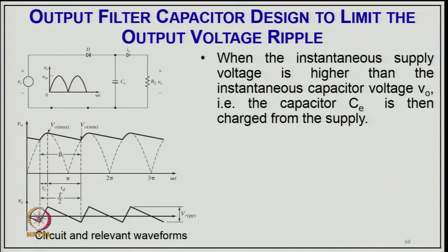And you will see this kind of waveform. As you can see here with the dotted line, this is the kind of output voltage we are getting across the load. Typically, in this duration, when your supply voltage becomes more than the capacitor voltage, the capacitor gets charged, and after that it gets discharged for a reasonably long time, depending on the capacitor value and the resistance. So, this kind of voltage waveform across the load you will get from this circuit. And from the average voltage, if you see the ripple voltage, it is over the average voltage, plus or minus, across the output.